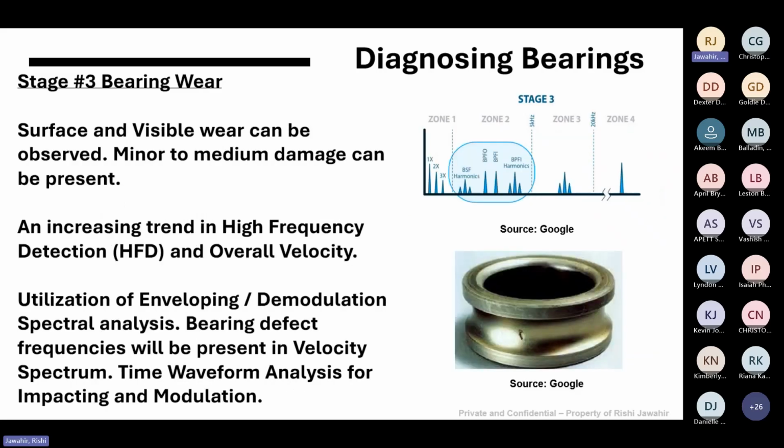Right, so getting to stage three, and stage three is typically where we want to plan our maintenance activities, all right? Because sometimes I've seen people diagnose a bearing at a stage one failure very early. They may see an increase or start to see high frequency detection, and say okay, well, peak view is high, shock pulse is high, and start trying to take down the bearing. And when they do pull down the bearing, there's nothing to be seen. The bearing looks good, looks healthy, looks perfect.